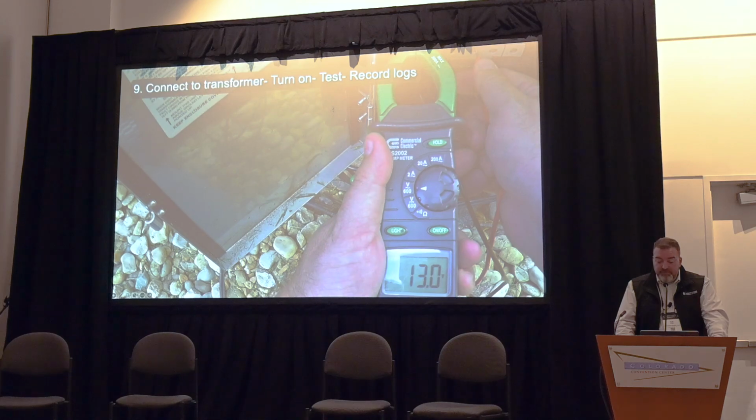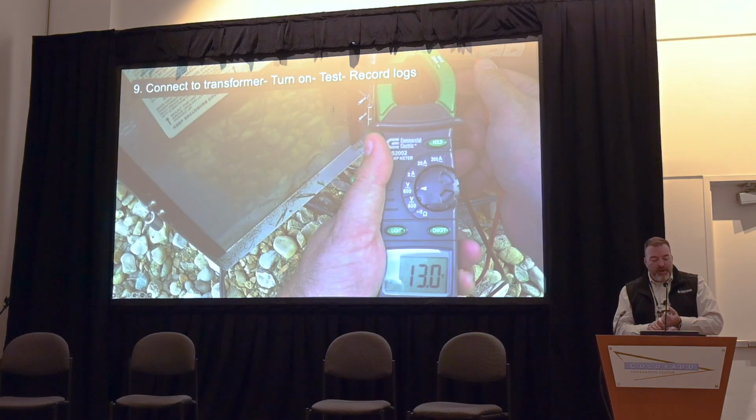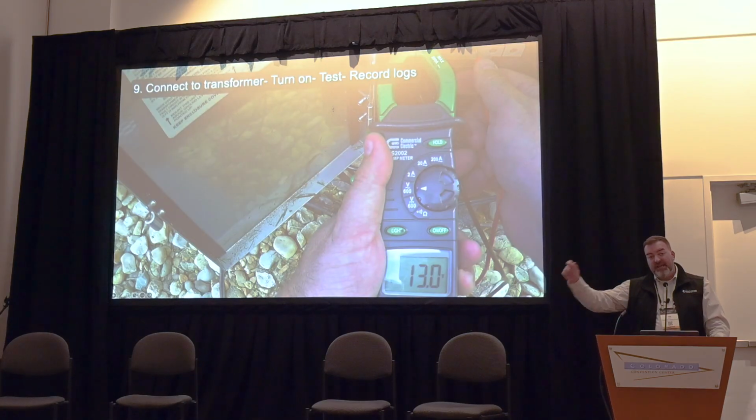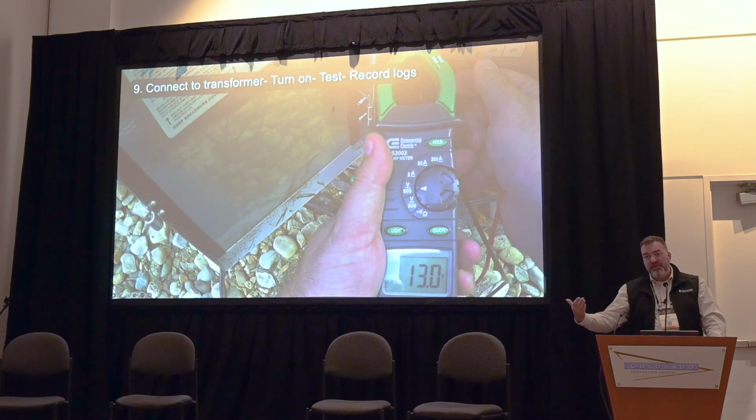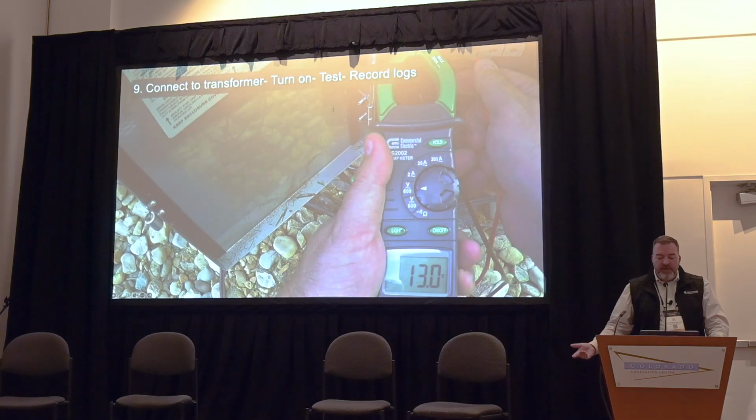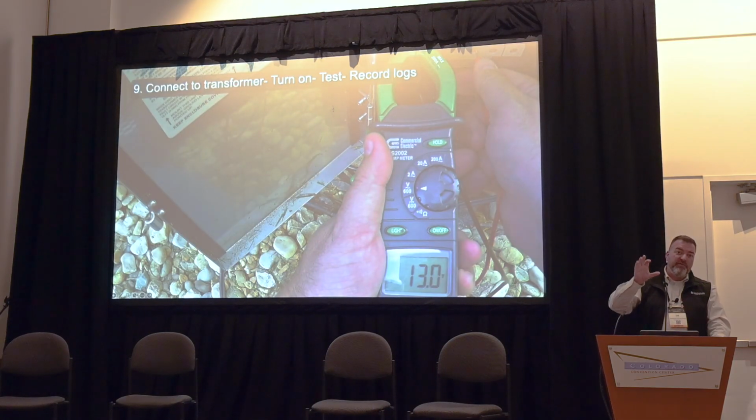And then for sure, once everything's done, you need to test it. For record documents, understand what you installed and how it went together. Check your voltage tap outputs, make sure they're rating right. Check your amp loads on each of the secondary low voltage wires. So you're going to amp clamp it and see how many amps it's pulling on the secondary cable on the landscape side. Then check the total amp load on the 120 volt side. You'll have a service test loop in your transformer.